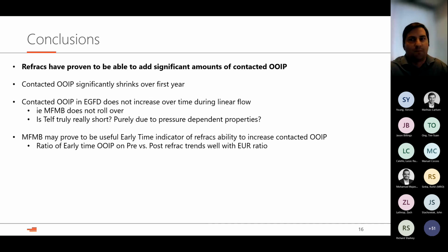So certainly, we proved up a lot of this work with the recent HFTS work that we did, seeing that we truly were, with refracts, able to create new fractures that we didn't have before, and able to see that we were not draining very far from those fractures based on the fluid that was left in the core, moving away from prop fractures. And so we knew kind of what that answer was in the back of the book for a lot of these refracts.